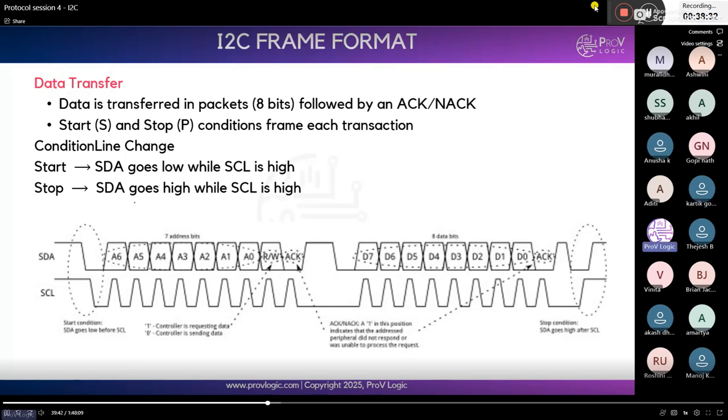How will we write SDA and SCL in the finite state machine? Like how do we write the expression? Ma'am, 0 0 is idle. When we have to start, we put SDA 0 and SCL 1, meaning 0 1.